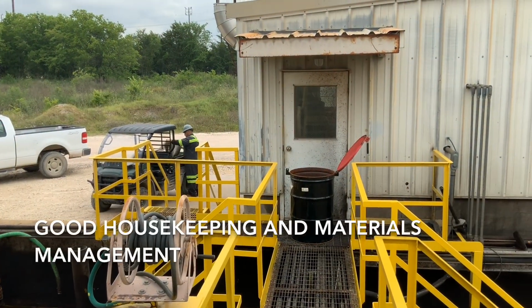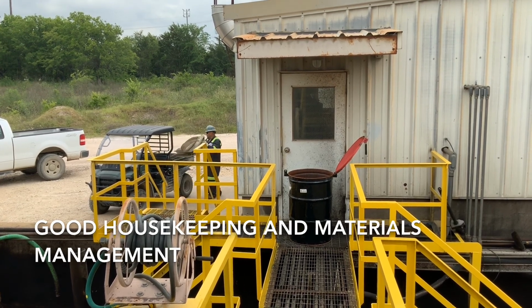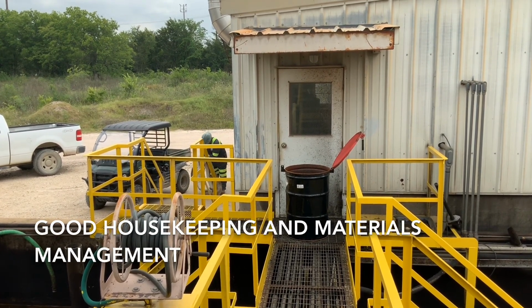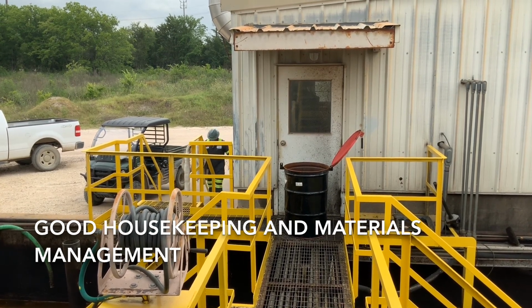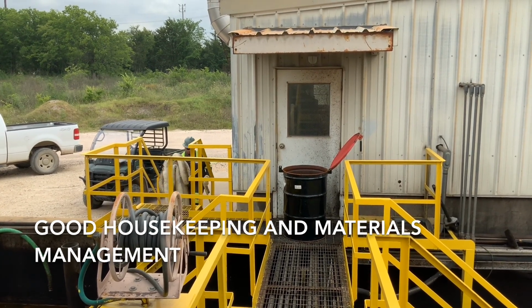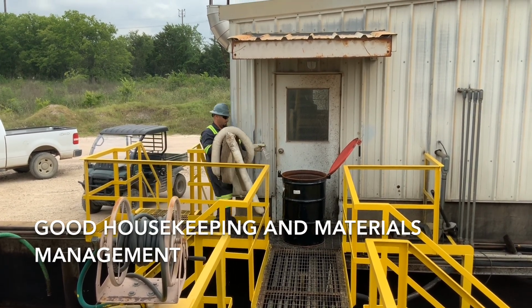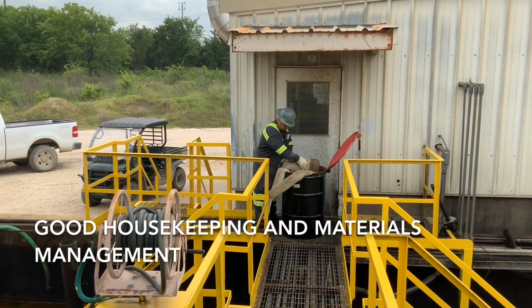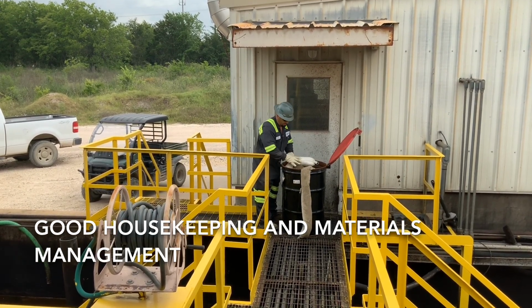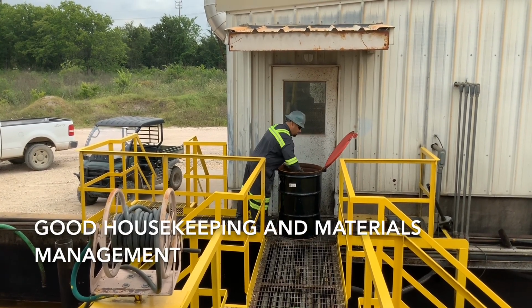Good housekeeping and materials management practices help reduce unnecessary stormwater pollution. It is best to store materials indoors or in secondary containment when not in use. Be sure to put supplies and materials away when they are not in use as well. Keeping containers closed when idle helps prevent avoidable spills.